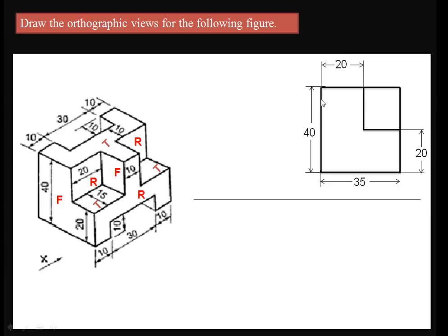That means from the last side of the rectangle, at a distance of 10 mm, there is a particular edge up to a particular height. So first try to draw a line with a distance of 10 mm. At a distance of 10 mm only the edge is taking place. So from this side locate that. Oh sorry, before that I'm drawing this edge.